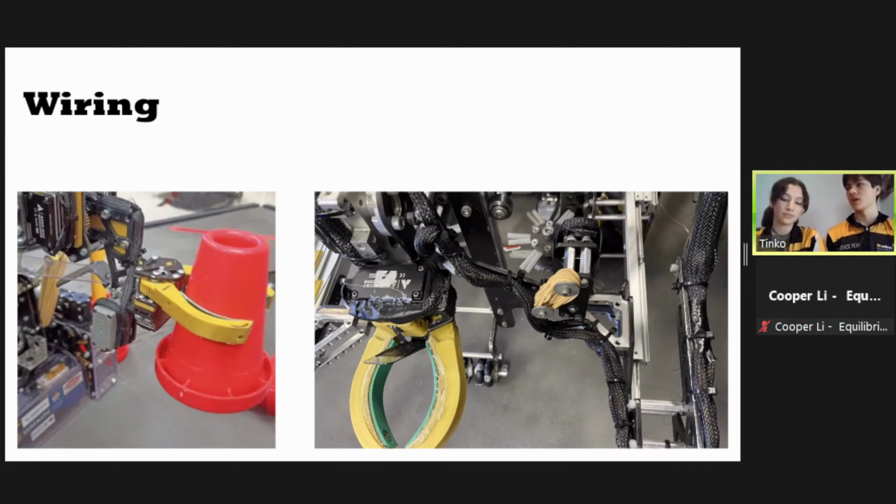Tinker was talking about servo wiring, but power wiring is also responsible for a lot of the disconnects that teams see. The Tamiya connectors are pretty bad as well, so we switched all of them out to Powerpoles, which we'll talk about more later.